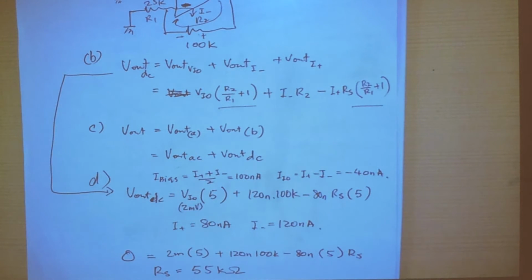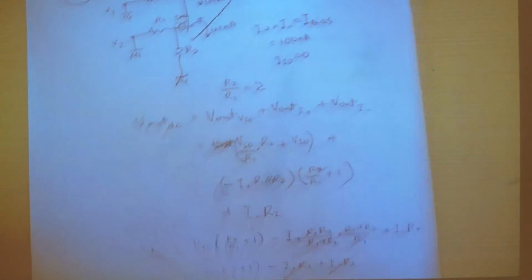So in question 3, we are given an op-amp connected as an inverting amplifier with a gain of minus 50, introduced by using two resistors, 100K and 2K, in negative feedback. And to the non-inverting input, there is a 2K resistor connected to ground. And again, this op-amp is a non-ideal op-amp, and it has I bias equal to 10 micro with I offset being 0, which tells you that I plus is equal to I minus is equal to 10 micro. And therefore, we can draw this as this.